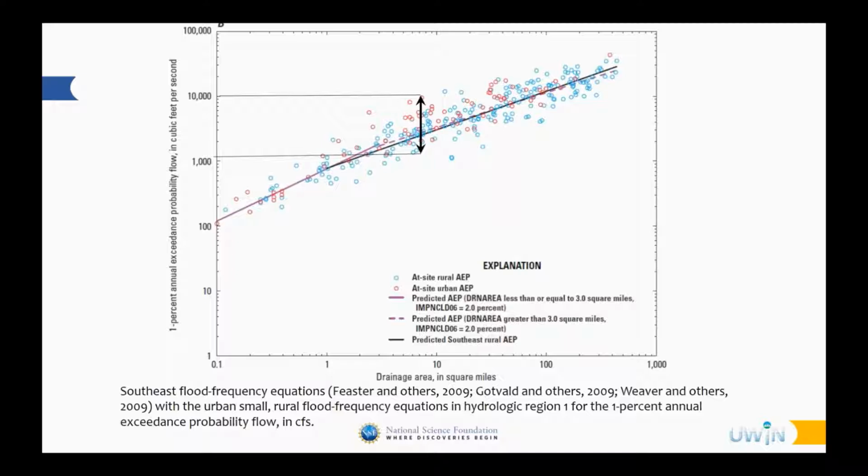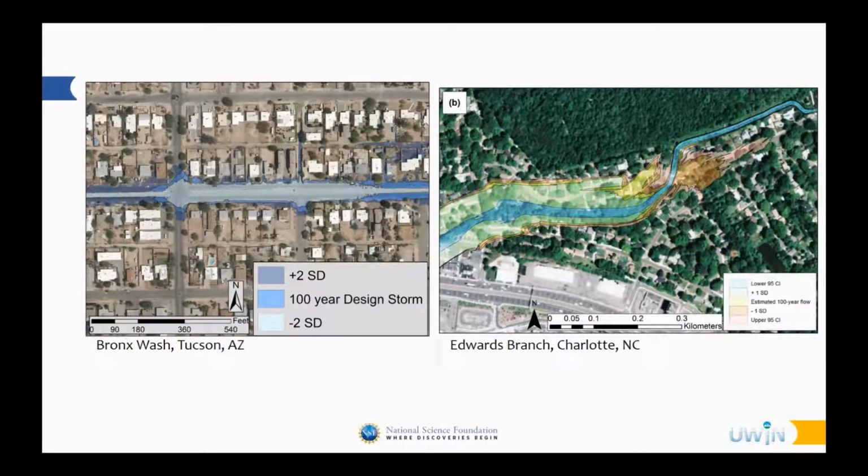The gauging network is kind of skewed towards higher stream orders, and so this uncertainty in discharge is one of the more obvious fundamental variables that we're going to explore in our Monte Carlo analysis here in a moment.